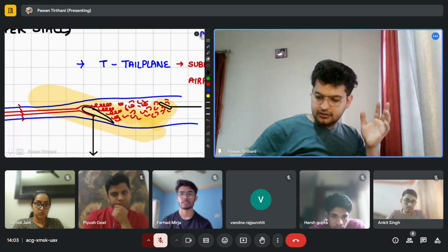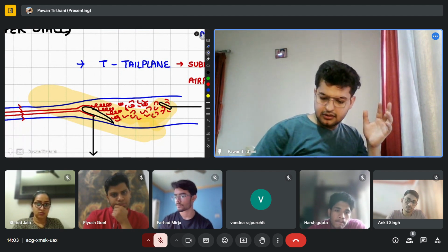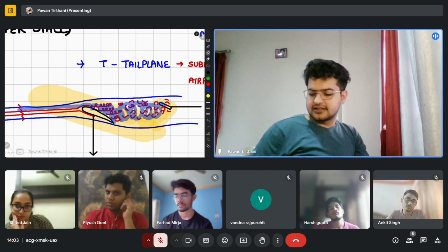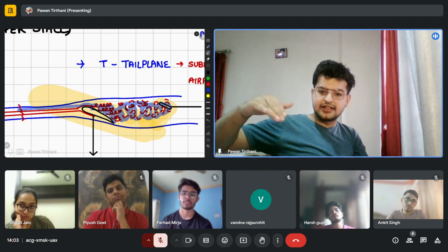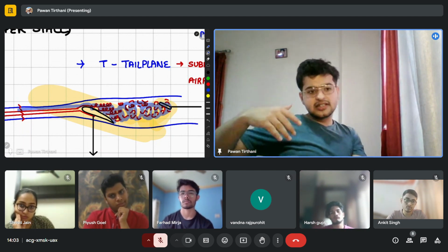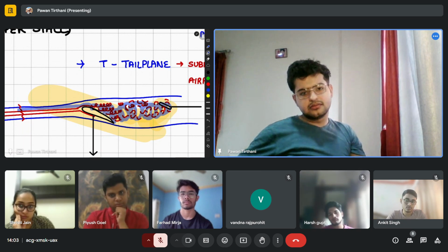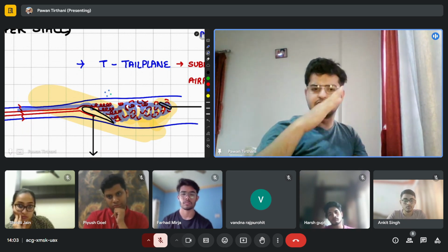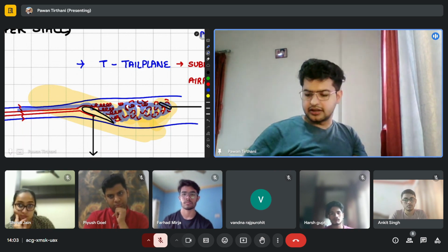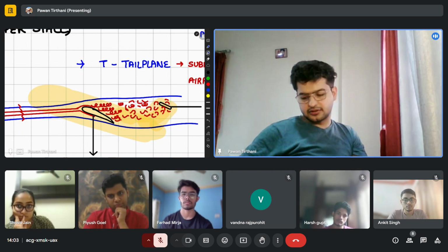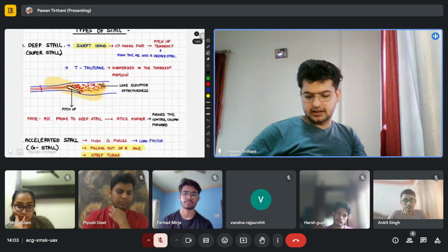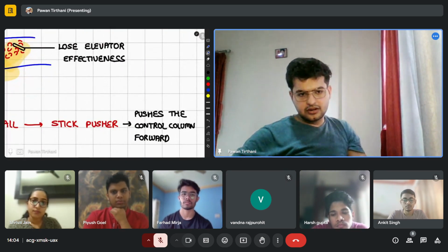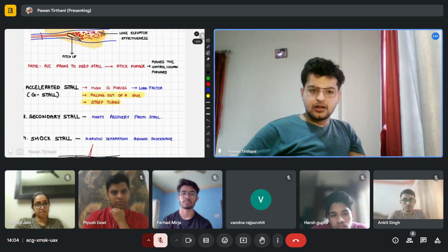Air is flowing over this wing, but now you have a turbulent airflow. Now your entire tailplane is submerged. अब वो सारा एलिवेटर यहाँ पे ऐसे ऐसे ऐसे भी हिलेगा तो वो नाक को नीचे कर पाएगा? नहीं कर पाएगा. So instead of the aircraft nose going down like this, the aircraft will go down like this. The nose will remain up. Clear? This is what a deep stall is. Aircraft is just blown to deep stall. You need a stick pusher, which pushes the control column forward with a certain amount of force.